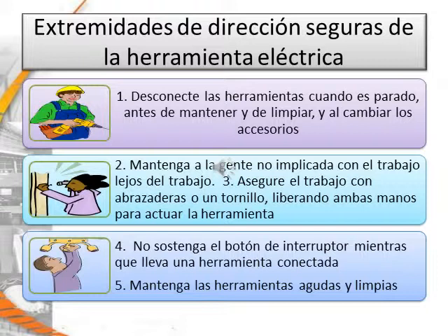Keep people not involved with the work away from the work. Secure the work with clamps or a vise, freeing both hands to operate the tool. Don't hold the switch button when carrying a plugged-in tool. And keep your tools sharp and clean.